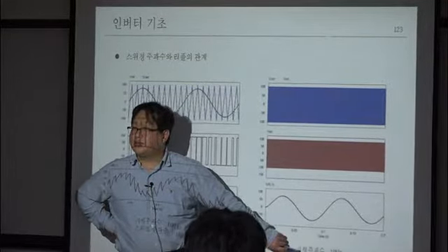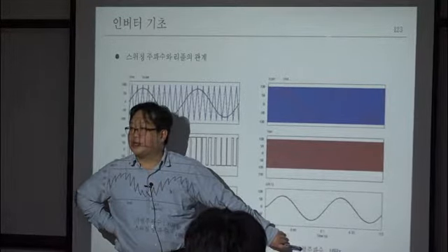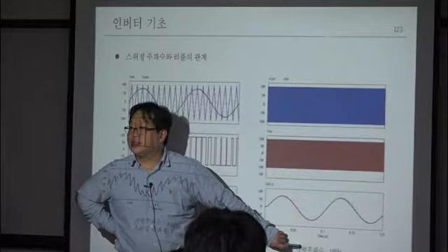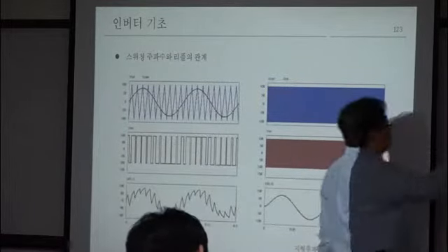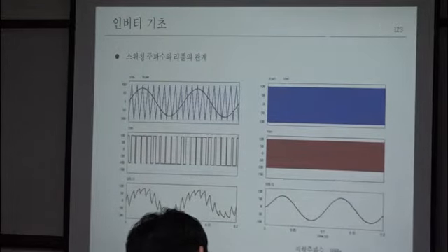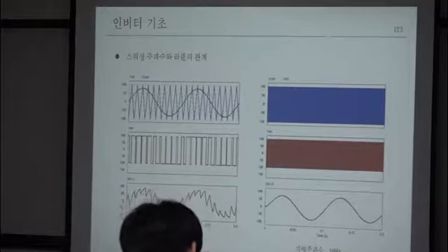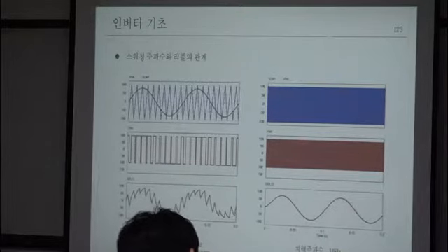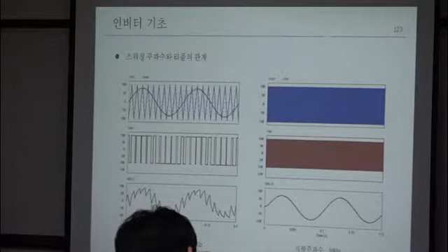But there are some limitations, because if you increase your switching frequency, then you also increase the switching loss. All switching devices have two types of loss. First one is conduction loss. Second one is switching loss.